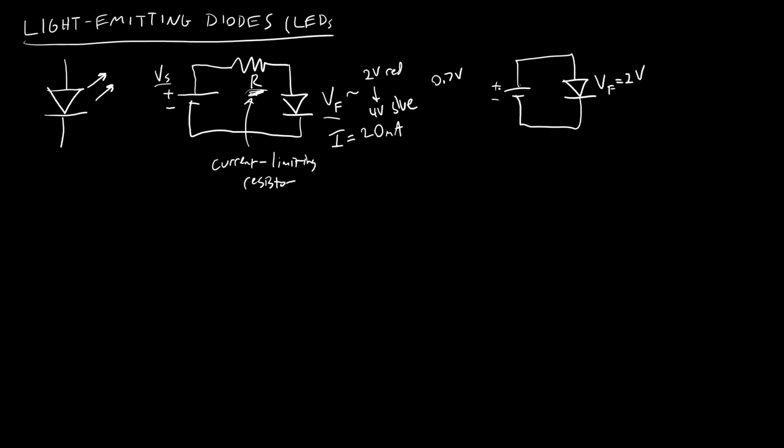On one hand, power supplies typically only come in certain values or common voltages. So for example, USB power provides 5 volts, and something like an Arduino that's running on USB power is going to use 5 volt or maybe 3.3 volt logic. Or if you are using batteries, individual AA batteries, alkaline batteries provide roughly 1.5 volts, but in reality that can be a little over even 1.6 volts when they're new and getting down closer to 1 volt as they drain, so that is not constant. So it's hard to find either, unless you have a laboratory grade benchtop power supply where you can turn a knob and select the exact voltage.